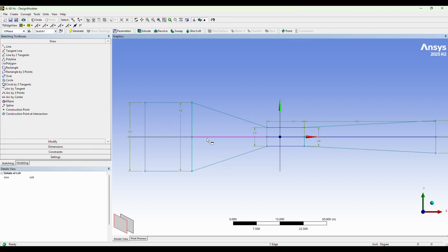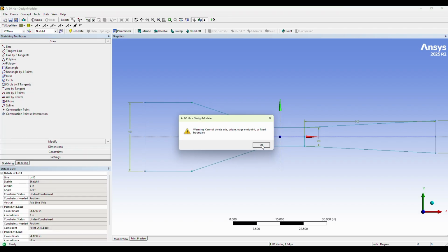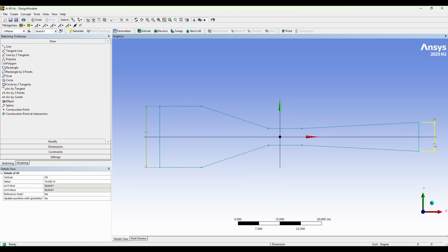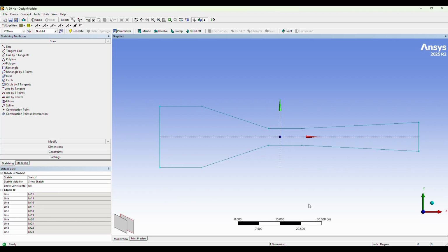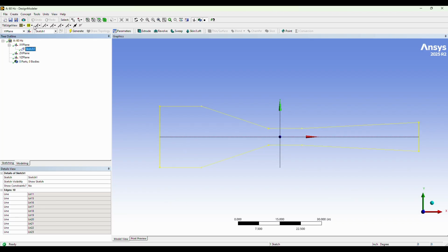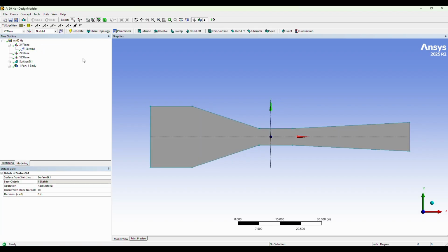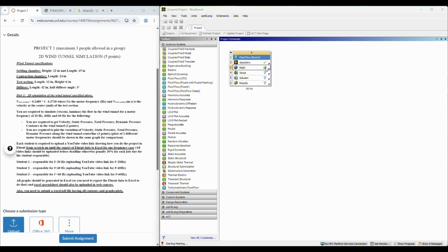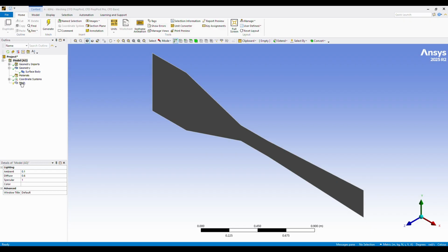So after we've connected everything, we're gonna go ahead and delete our initial structures, and then we're going to generate the mesh by going into concept and then surfaces from sketches, and then now we have a flat plane but it's filled, and we can go ahead and add more resolution in the meshing. We're going to generate a method that triangulates it.